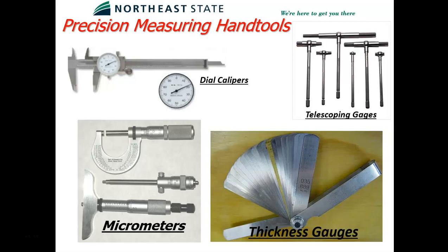Telescoping gauges, top right. Those are pretty neat devices. You don't see those very often, but we've got some in the lab, and I'll give you hands-on with those. Quickly, the explanation of those. Look at the middle one there, the biggest one. You get a little plunger sticking out both ends. You push that in, it's spring-loaded, and it'll pop back out.